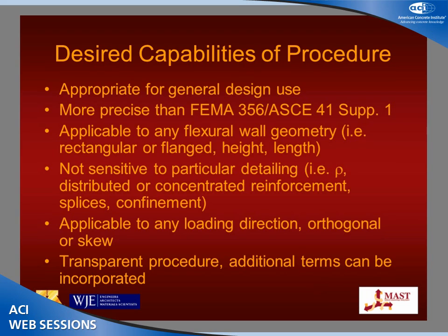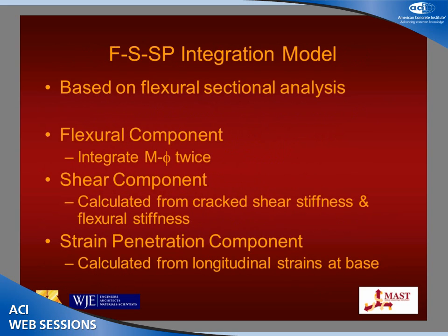We wanted it to be generalized enough to be applicable to any flexural wall geometry, including rectangular or flanged walls, not necessarily symmetric walls, any height, any length, the only requirement being that it be a flexural wall and not a squat wall. We did not want it to be sensitive to a particular detailing. We wanted it to be applicable to any loading direction, whether that be orthogonal loading or skew direction loading. And we wanted it to be transparent enough so that we, or others, could add terms as needed.